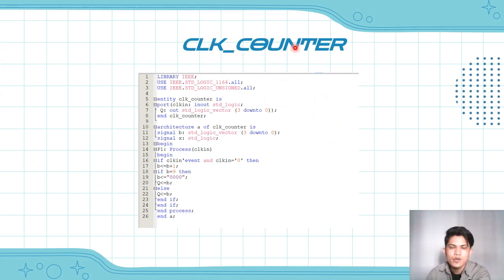Right, for CLK counter coding, first we declare the library use the same as before, and then for the entity we name it as CLK counter, and then we define the port where CLK again is the input port and Q as the output port. And for the architecture we name it as A, and it contains two signals B and X, which are declared as standard logic vector and standard logic respectively.